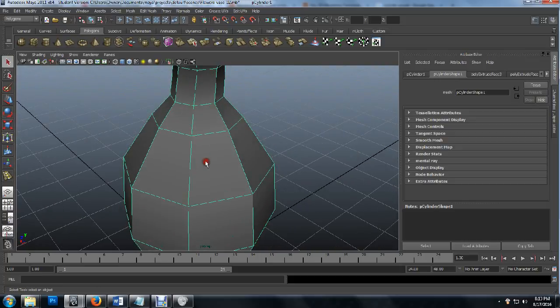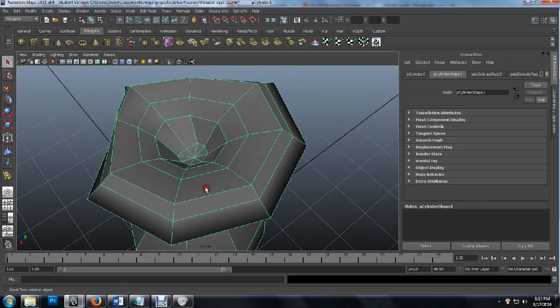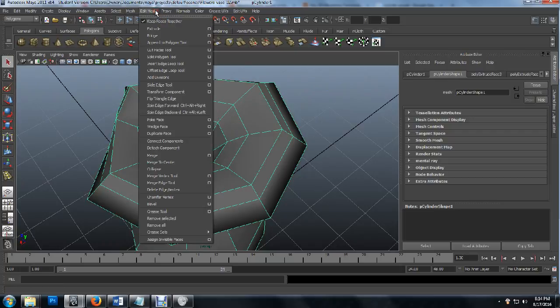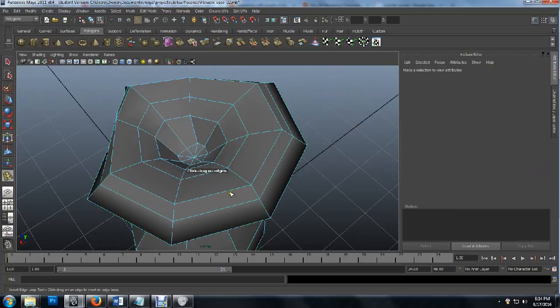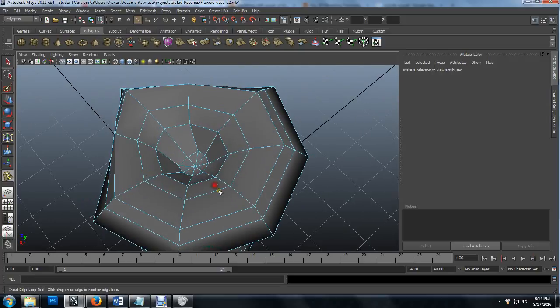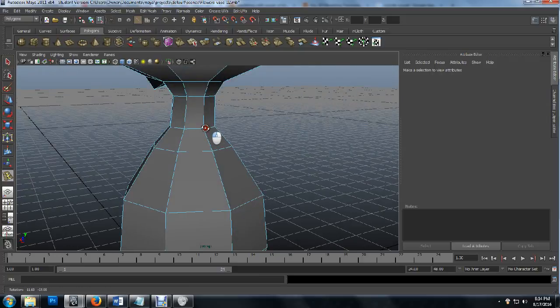And I'm going to show you what'll happen if you try to add an edge loop to this, and there's a triangle. I'm going to go up to my mesh tools. I'm going to grab edge loop, and I'm going to add an edge loop just right here. Normally if I add an edge loop, it'll go all the way around. Well, same thing if I add an edge here, it should, and you don't have to copy me in this, I just want to show you.